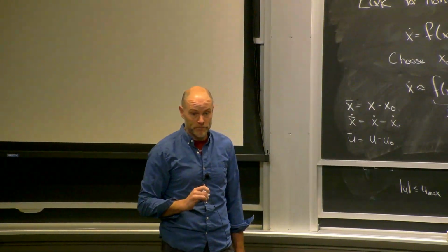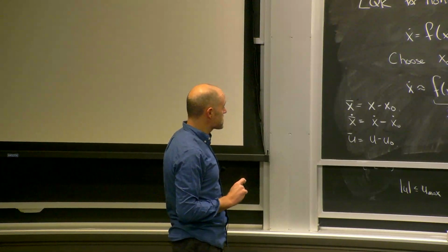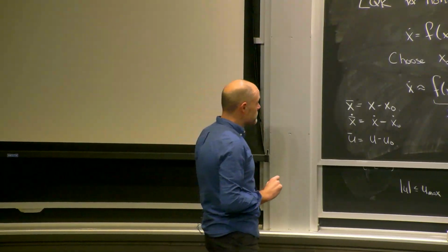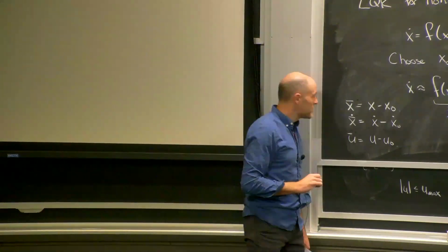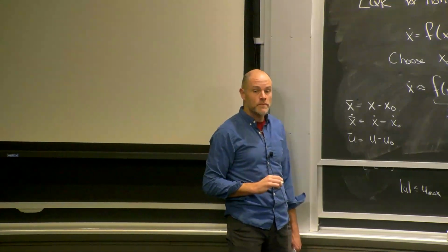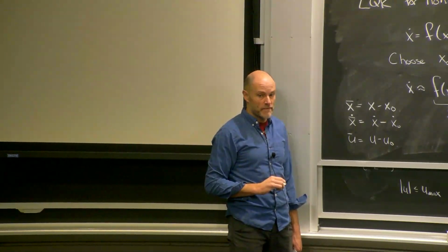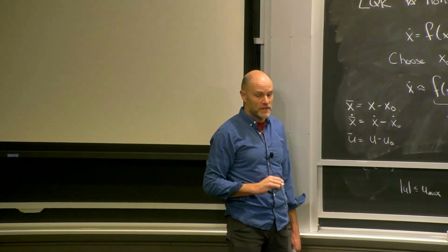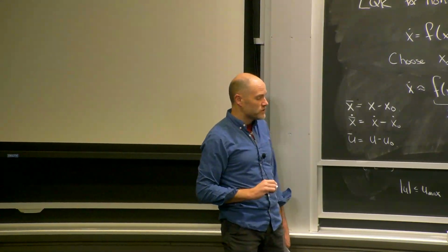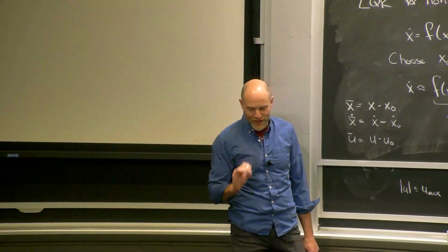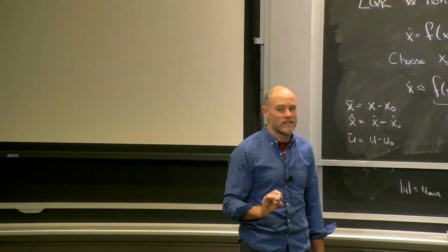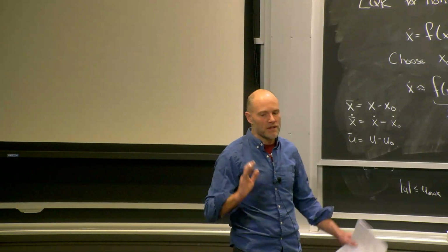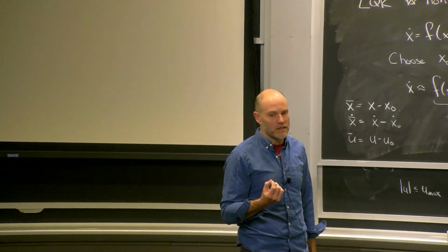Can you just expand one more time on x dot minus x dot not needing to be 0? So I can think of, like, for an aircraft, you linearize it around a trim point. Yep. So the velocity is constant. Yep, that's a great example. So the language of trim conditions is slightly different than the language of stability. You can be stable to a trim, but that's different than being stable to a fixed point.